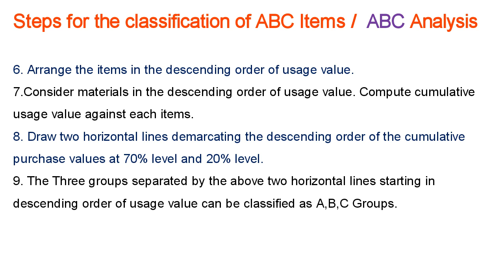And now what we do is we draw two horizontal lines demarcating the whole materials into two parts. One will be drawn at 20%, and another one will be drawn at 80%. Or in other words, since we are coming in descending order, we'll be starting with the highest, the material with the highest price, right? So we'll first draw a line which demarcates a few items which constitute a major portion of the total material cost. Say 70% of the cost is grouped by the first demarcation line, and then after some position, we'll draw another line which will demarcate the materials into categories B and C, like that.